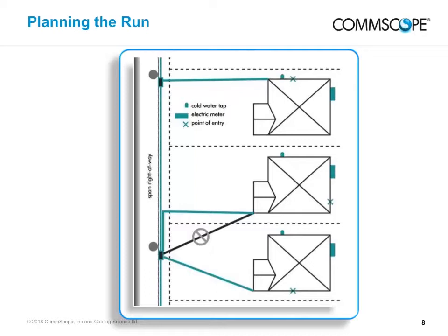Know your ROW, right-of-way. The most direct route may not be the legal route. Make sure the route you're planning runs only over the customer's property. Generally, you can follow a parallel path to power or phone lines. However, under no circumstances lash your drop to any other cable. While most spans have taps located next to the poles, you may occasionally find a tap in mid-span. This may be helpful in avoiding ROW issues.